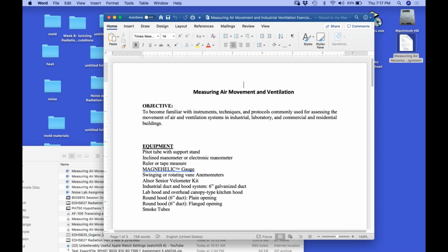These systems by nature are inefficient that way, that it's pulling air in from all these different sides. So you lose a lot of the energy from this system. A lot of the velocity is lost, and you want to capture the energy, right? So this might be only 10 feet per minute. This might be 20 feet per minute. This might be 100. You get very close to this to get to the velocity that you need to capture the material that you need to capture. So depending on what the material is, you might need a lot of air moving through this in order to capture the dense, heavy part of it.